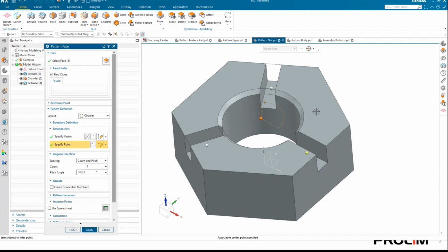And there we have it. Now it's on every other face. It's divided that pitch angle to 120 each. Now, of course, you can put this in as an expression, and I will talk about that soon. But in this instance, this is just a quick and easy and very dirty way of doing it.